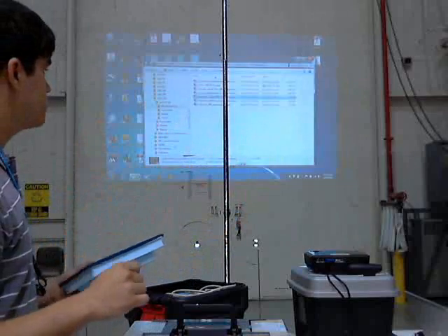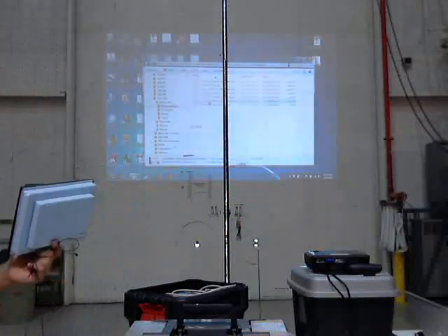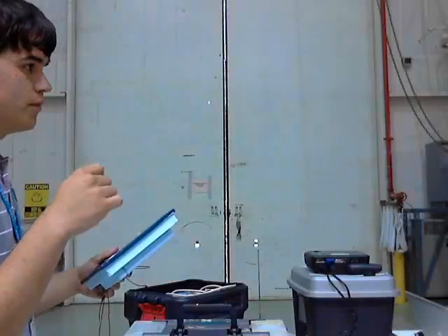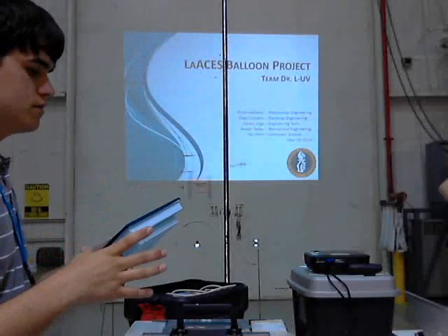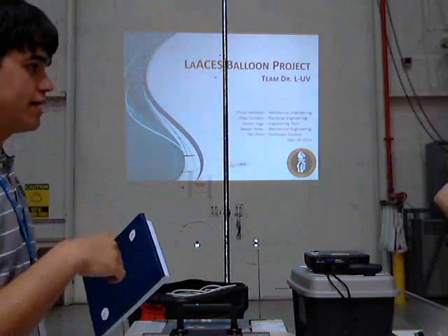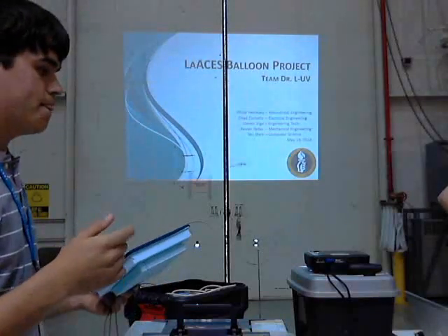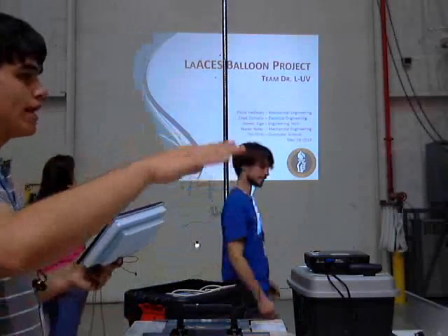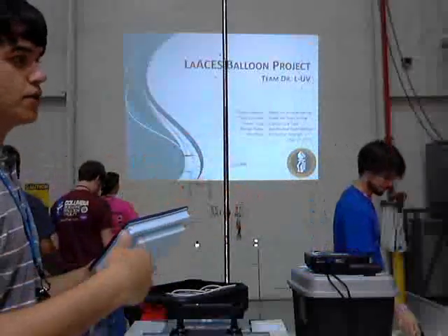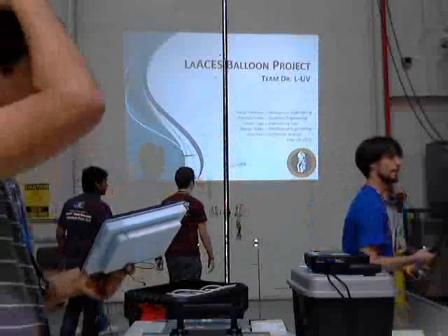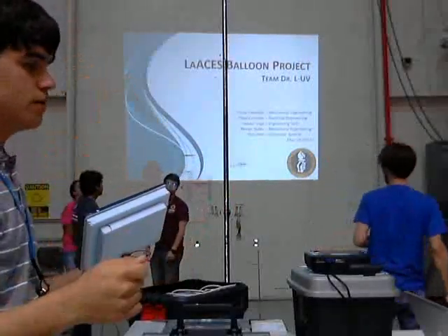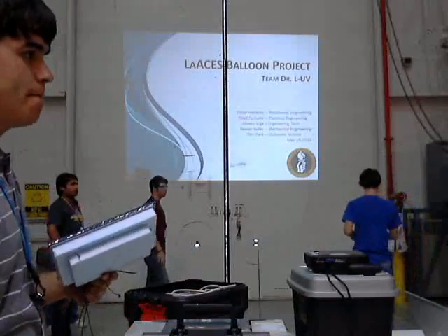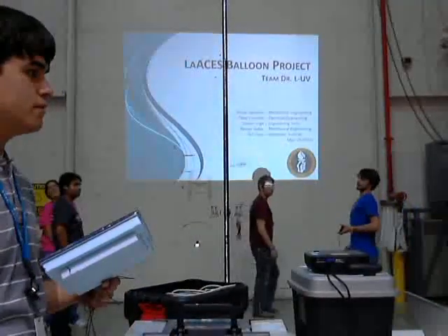So with our toggle switch, which we forgot to mention, it's wired. We desoldered an LED off the board, off the balloon sat board, and wired the switch in there as a pull down, so that when it's one way, the data is writing to the EEPROM, but this is all in code, the code's reading the pin section. So when it changes over, it won't write data to the EEPROM. Okay, I understand what you're doing. I wanted to come and look at it. Okay.